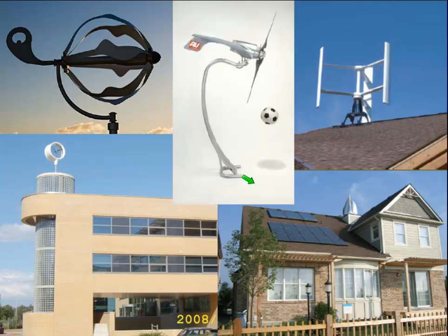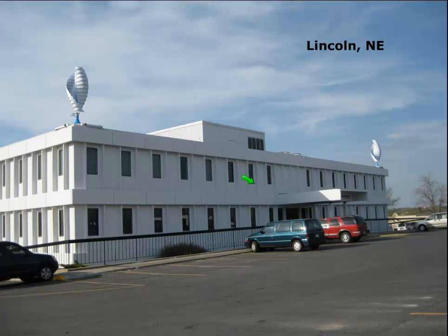Okay, here's what I know everybody's excited about. People are excited about small wind turbines and putting them on buildings. And I am absolutely not excited about small wind turbines and putting them on buildings because of 2 of the reasons I already showed, which is there are low wind speeds, so you don't produce much power low off the ground, and number 2, you have turbulent winds, which are slower and, again, not producing much power. So let's just give some examples. I like examples. Here is a Savonius type of wind turbine put on a building in Lincoln, Nebraska.